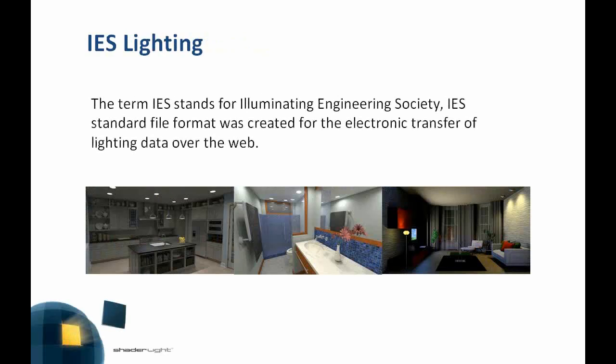We're also going to look at IES lighting. Now IES stands for Illuminating Engineering Society. The explanation that's there is more complicated than, to be honest, you need to know. What you need to know with IES files is it's pretty much real-world lighting information stored in a file. And Shaderlight can read this file, and then it can produce the results as this would look in real life. We're going to have a look as we go through, and hopefully you'll get a full understanding of where you can get these files from, and also how they work inside Shaderlight and how they can benefit you.